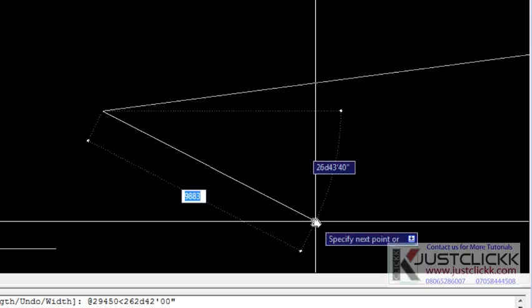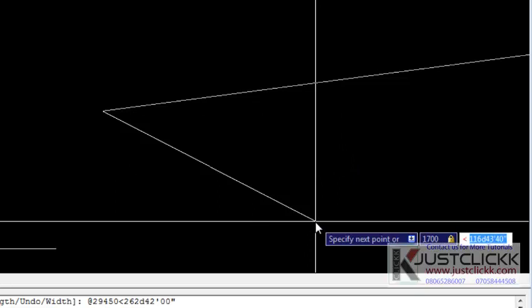So I will press in the 1700 and hold down my shift key to get the less than sign, and then I'll input my angle here, which is 171, end up with degree, and then my minutes are actually 42, and end up with an apostrophe by the side, and then my seconds are 00. Hold down the shift key to get a quotation mark.